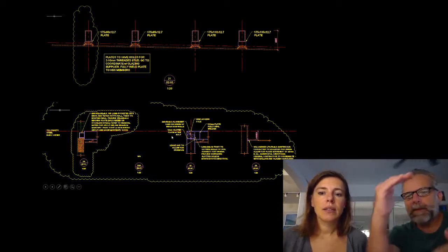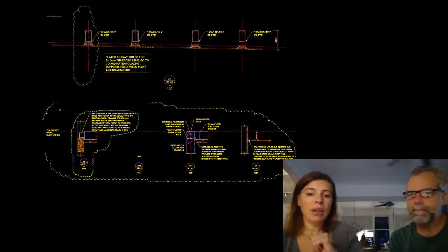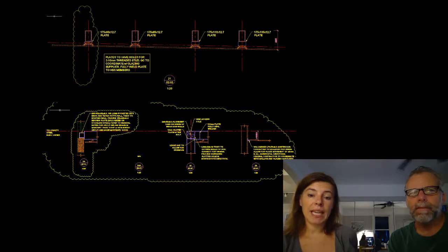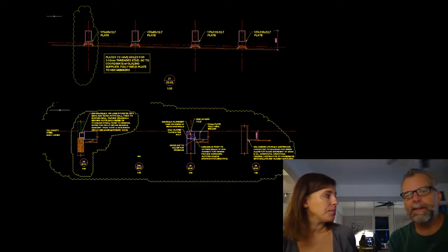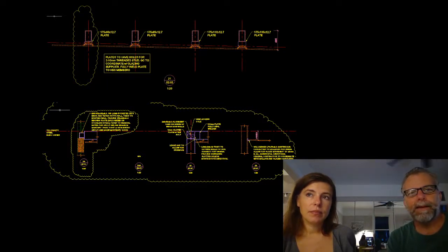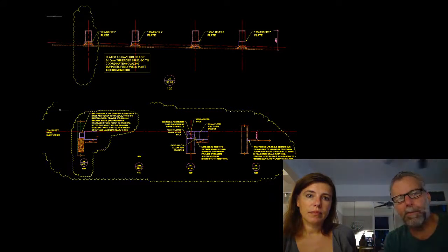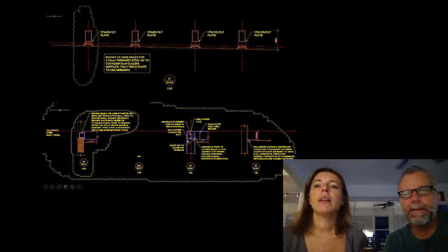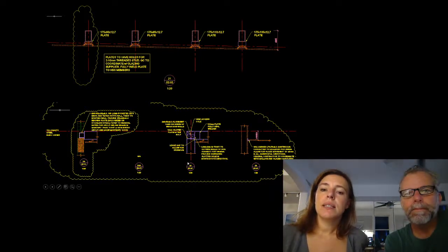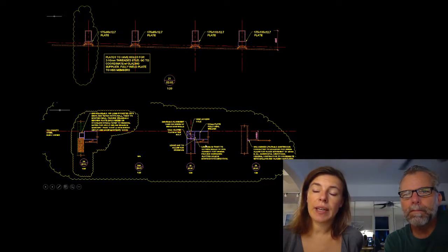Well, and they didn't want a big escutcheon plate. Right, one of the easy things to do is clip something on the outside, but they didn't want to see that. They wanted it hidden as much as possible. That's right. They didn't want the connection to have a profile any larger than the actual member that was being connected, and so we did this kind of reducer into a smaller pocket so that the brick would be clean around it. And then this is the detail that we did for that moment connection of the beam to the column, where the entire thing happens internally.